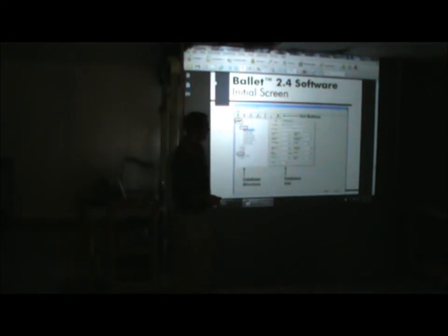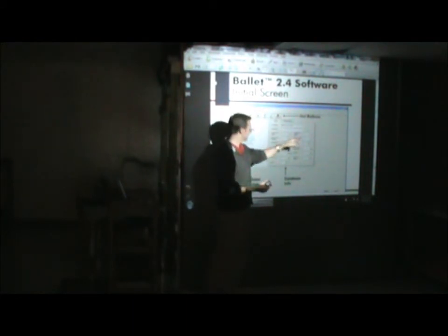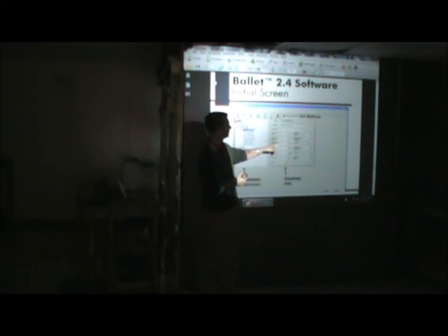So you have that database structure, and within each task, you put a little description in there, what the vertical height is at the beginning of the lift, what the vertical height is at the end of the lift, the moment arm at the beginning, which is again that distance, the moment arm at the end, the weight, the coupling, asymmetry. Looks familiar, doesn't it? Those are all the modifiers of the lifting equation. It's the NIOSH lift equation, exactly right. But this risk model uses the moment arm information that you input with the analysis.